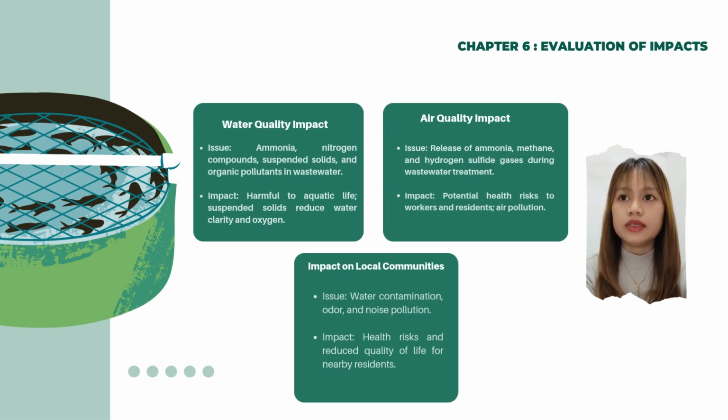Evaluation of impacts. The first one is the water quality impact. The issue is ammonia, nitrogen compounds, suspended solids, and organic pollutants in wastewater. The impact is harmful to aquatic life. Suspended solids reduce water clarity and oxygen. Second, air quality impact. The issue is release of ammonia, methane, and hydrogen sulfide gases during wastewater treatment. The impact is potential health risk to workers and residents.